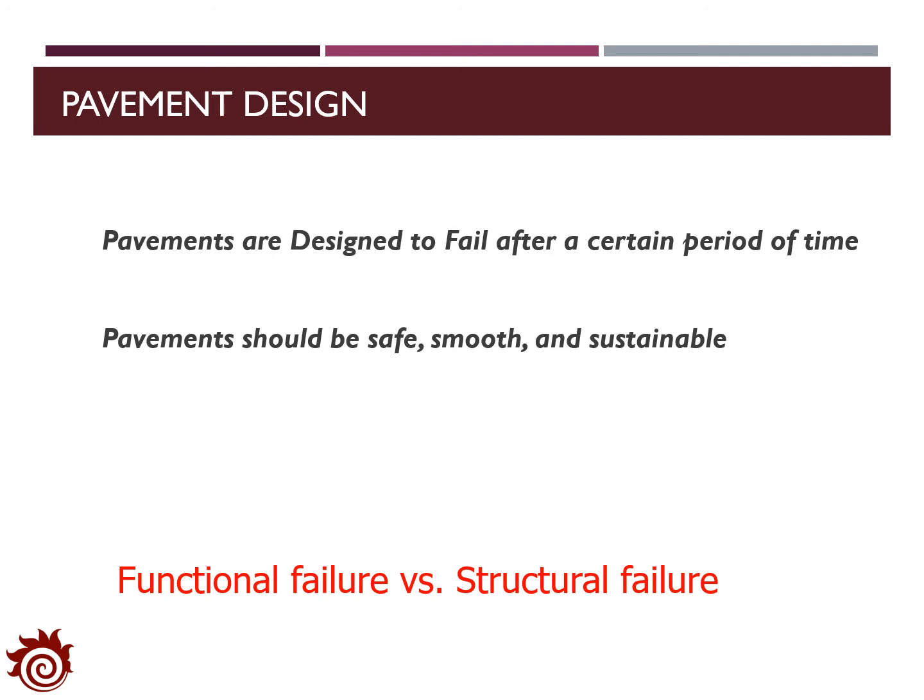And there are two types of failures: functional failure and structural failure. The functional failure occurs when the pavement is unable to carry out its intended function without causing discomfort to drivers or passengers, or imposing high stresses on vehicles. The structural failure occurs when the entire pavement structure collapses, or one or more pavement components are broken down, and this will make the pavement unable to sustain the load imposed on its surface.